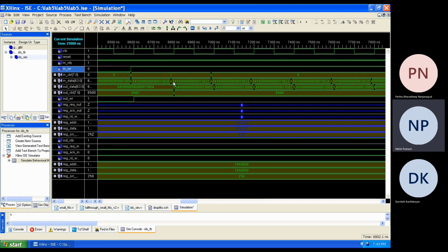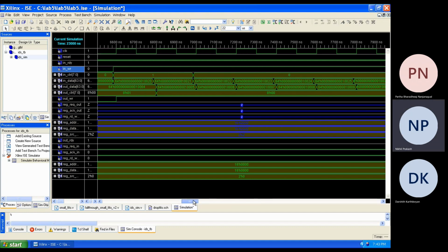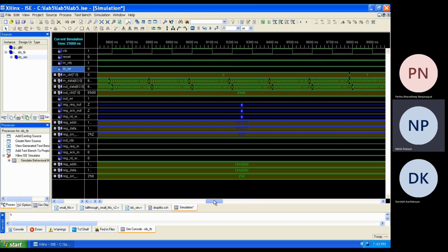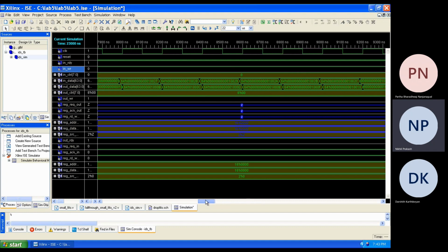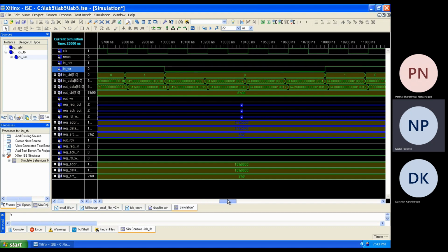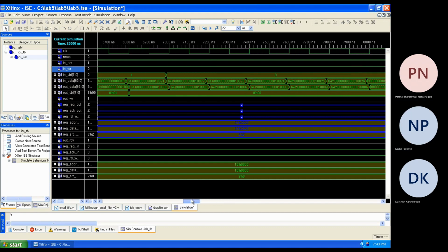This is the actual first word of the data packet, and then it's 0 again, indicating the middle range, and then this is the last word of the data packet, right? Again, none of the data words match our pattern. So the target pattern is not there, so even this data packet should come through, right?